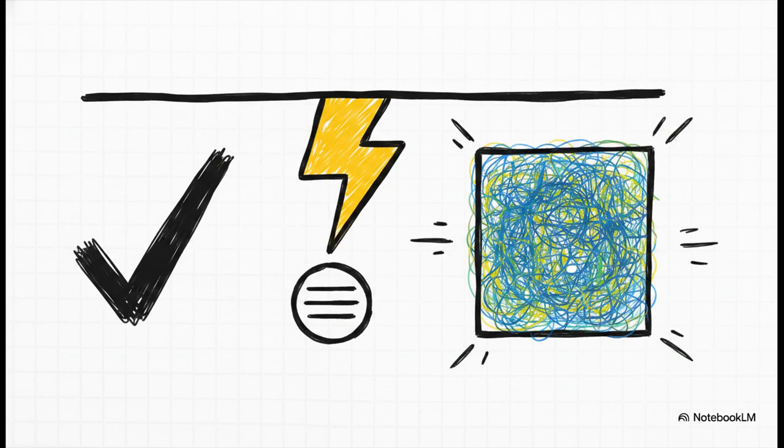If you guessed single line to ground, you are spot on. LG faults are the industry standard basis for these studies because it is the only common fault where the zero-sequence network is mathematically and physically guaranteed to be active and dominant. Think about it. A three-phase fault has no zero sequence. An LL fault has no zero sequence. You absolutely must use the series interconnection of the LG fault to properly simulate and coordinate your ground relays.